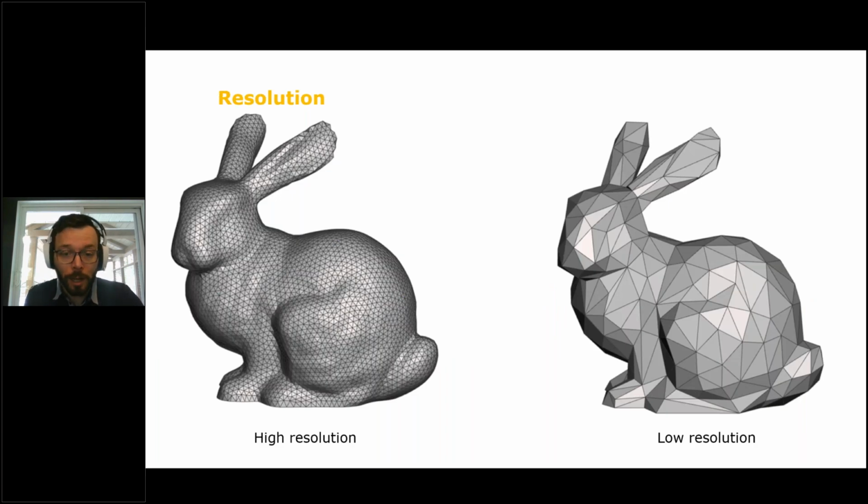Now, the differentiation is also the resolution, or the capability to capture finer details, often confused with accuracy, by the way. You typically need a good accuracy to get a good resolution, but you can have an accurate scan without a good resolution. With more resolution, you see finer details in a scan, for example, holes, brackets, tiny details. Now, more resolution does not necessarily mean better details.